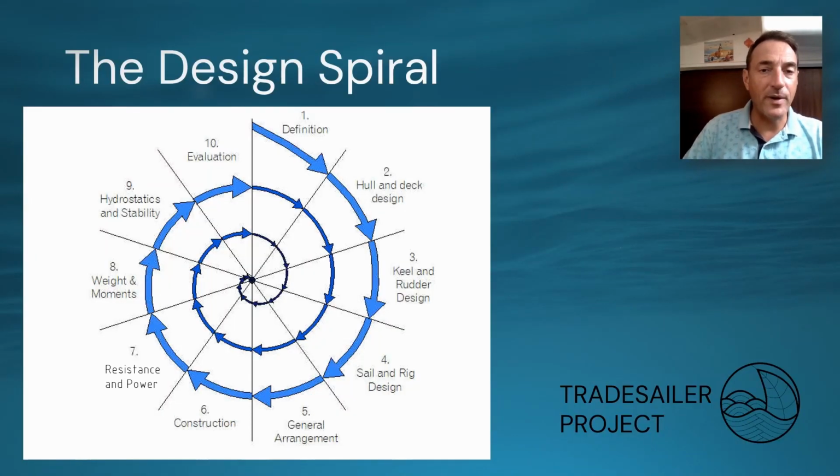And this is the design spiral I set up for this project. We start at the left top and we go a few loops around. We do this so we can re-evaluate and adjust until we get a working set of parameters. The parameters are connected to each other. So different parts of a ship design are connected to each other. So if you adjust one, another one will be influenced as well. Therefore, we need to do multiple loops and get to a good endpoint. A bit like sanding. You start with coarse sandpaper and you work your way down to a final grit.